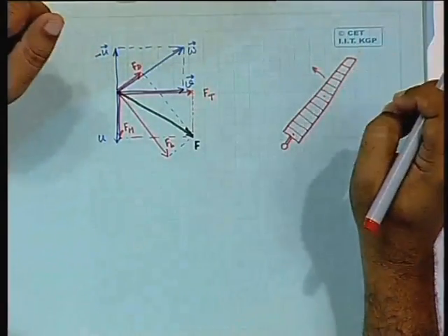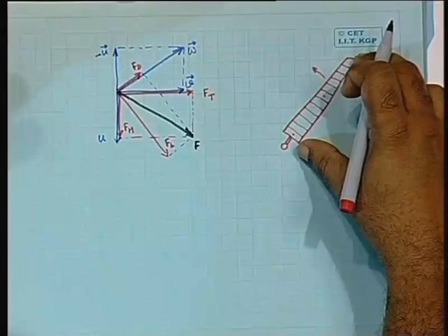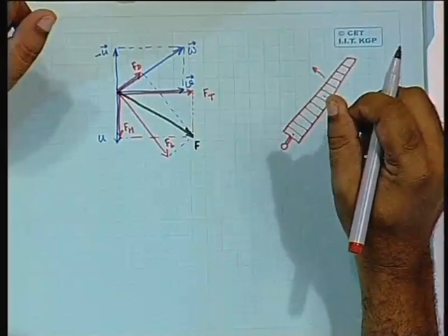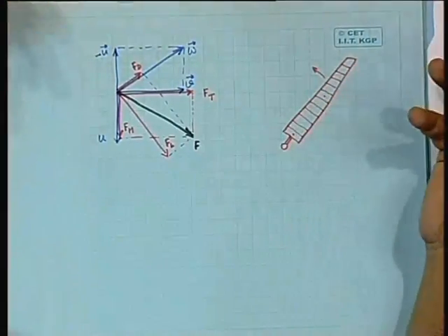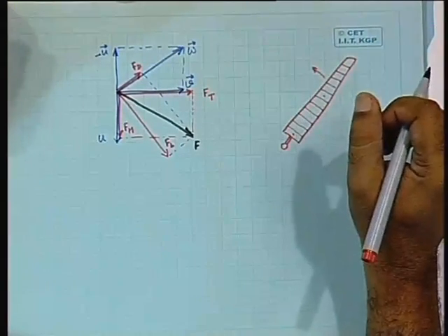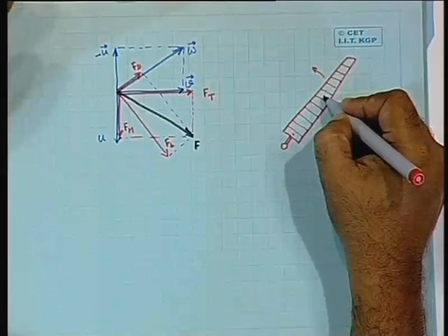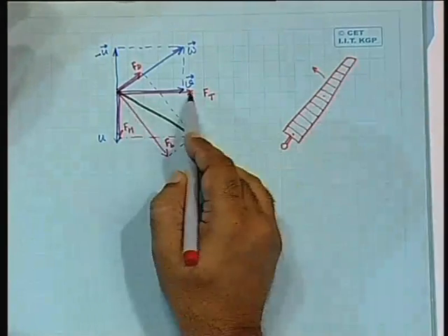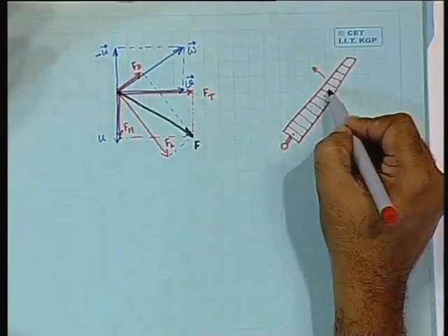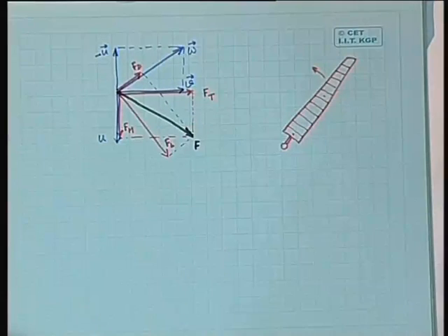While doing the calculation by hand, we often divide the blade into a small number of sections, say 3 or 4, and we can do the calculation by hand. But often the actual calculations are done by computers, where you define many small sections, and for each section the calculation is carried out, and then you can add up. For example, if this one produces a certain amount of thrust, this force, this one produces another certain amount, then the whole thrust experienced by the blade will be simply the summation of them.